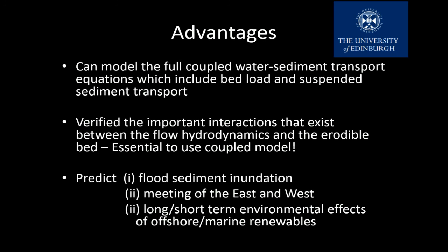But some of the advantages are that we've shown that it is possible to model the shallow water sediment equations in their fully coupled form without needing to do the manipulations that have been done previously. And it's clear that the interaction between the flow hydrodynamics and the erodible bed is completely coupled for these very rapidly changing flows, so it's necessary to use a fully coupled model. And this kind of model can be used for flood prediction, especially flood sediment prediction.